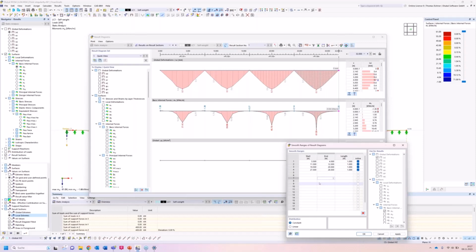You can imagine pressing your finger with your other finger. That's like a distributed load. But a nodal load would be more like a needle, which you press onto your finger. And it's rarely happening on buildings.